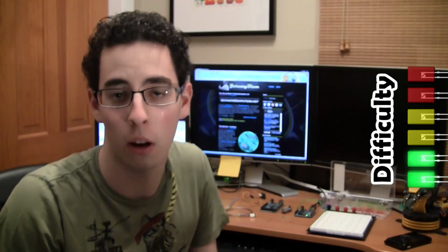We're on a roll here. Today we're going to be talking about analog inputs to the Arduino. I'm going to talk about setting a reference level for the analog voltage, taking an analog voltage in from either a pre-made sensor or building one yourself using a variable resistor and a voltage divider, which is something we talked about last week. And then we'll talk about mapping those values to different values in the Arduino programming language, using it to control LED brightness, which is an analog output, and a few other applications.